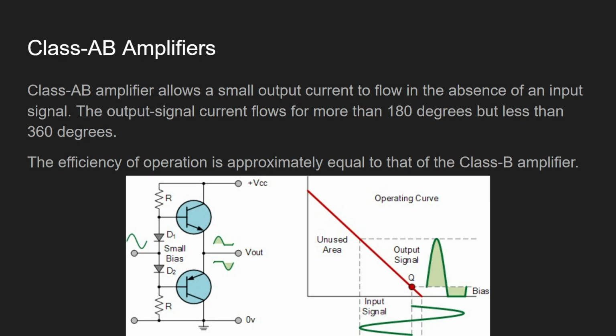They will see the phase difference. So you see that it's more than 180 degrees. Class AB will have a zone. This is the crossover zone. At some time point, they will have two amplifiers working at the same time. So Class AB is very good, but they will need some more technology for the manufacturers to do the handover very well. If the handover is not done very well, you will hear some weird signals.